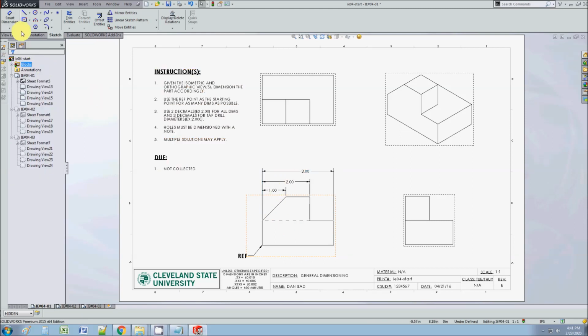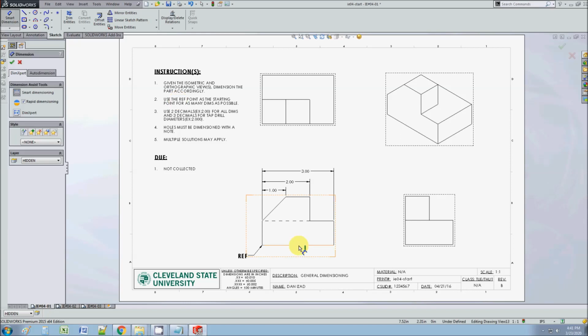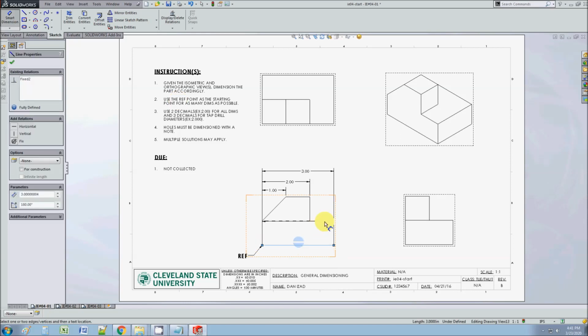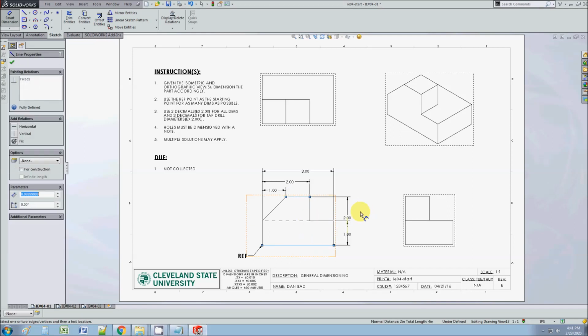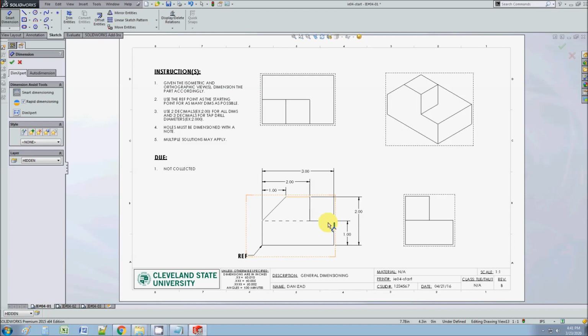Now what I'm going to do is do the same thing in the vertical direction. So here's my ref point again, and I'm just going to keep building till I reach the top of this structure. I've defined the front view, but I need to define the depth, right? And I can't really do that with the front view. So I gotta pick either the top or side view. So I can do either or. I'm just gonna pick the side view, alright? I feel like this is a little bit best described. But it's not a big deal if you pick the top view. It's really not a huge issue.